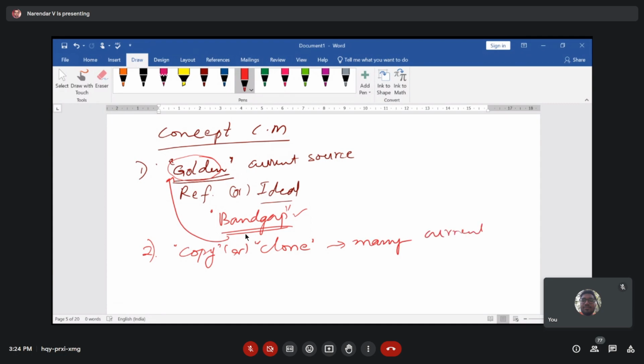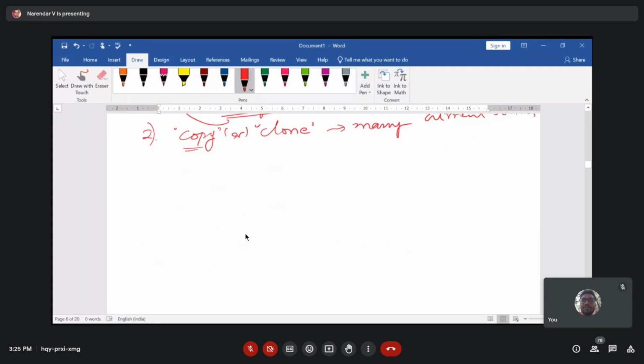Let's say you have a reference current, I reference, and then you clone the I reference and generate I1, I2, I3, I4, and I5 as per your requirement. And this I1 to I5 or I10, all are the same as your I reference current. And this I reference is independent of your temperature variation and supply variation. That is what we try to do now.